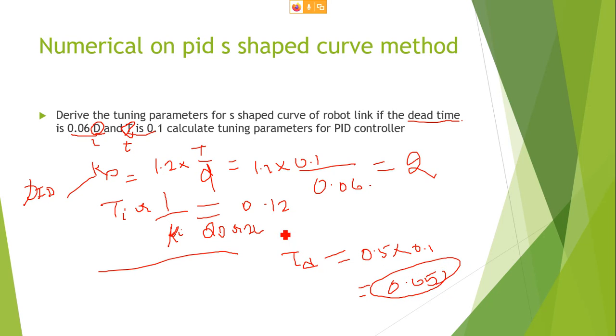So using these three parameters, Kp, Ti and Td, we can estimate the tuning numbers. If you set these values as the constants in the proportional controller, automatically the system will perform with the optimized parameters of Kp, Ki and Kd, or Kp, Ti and Td. Both are the same, right?